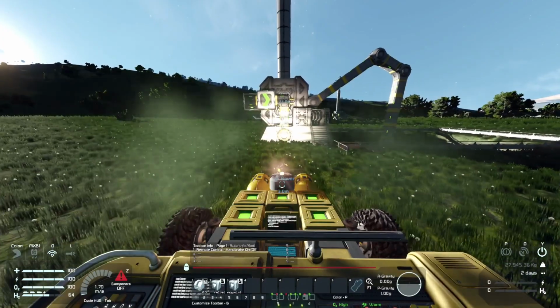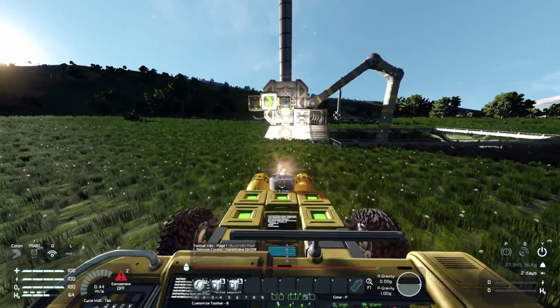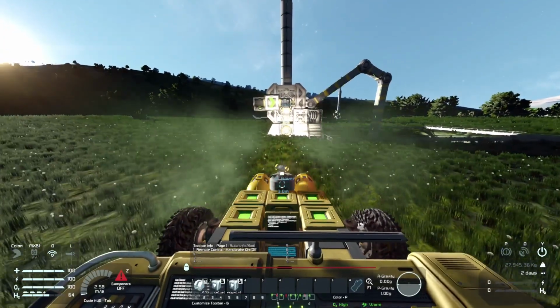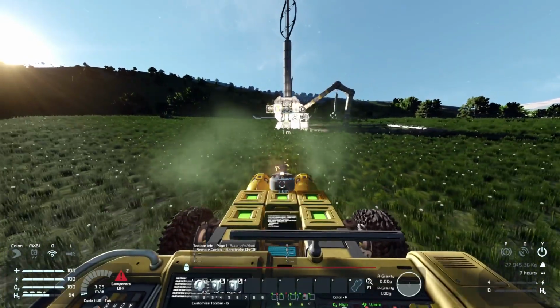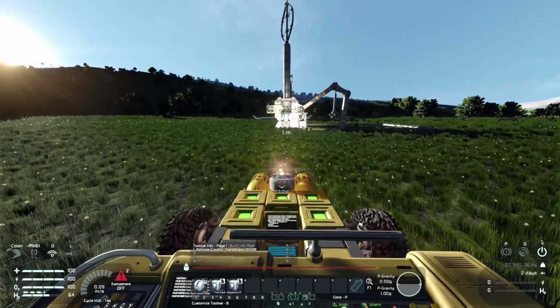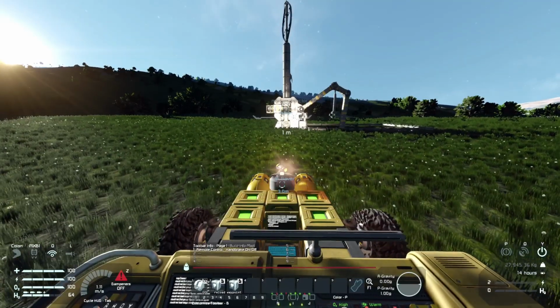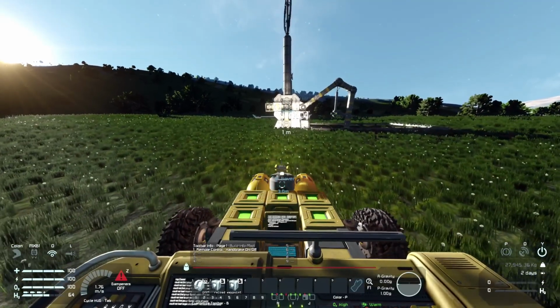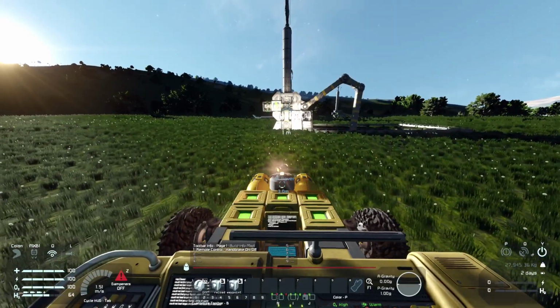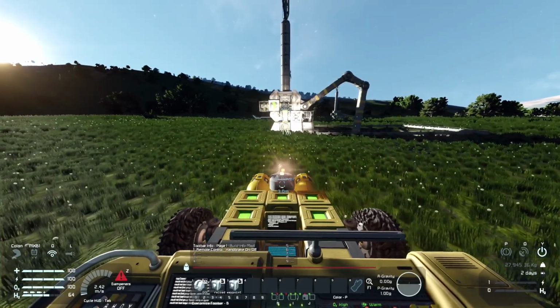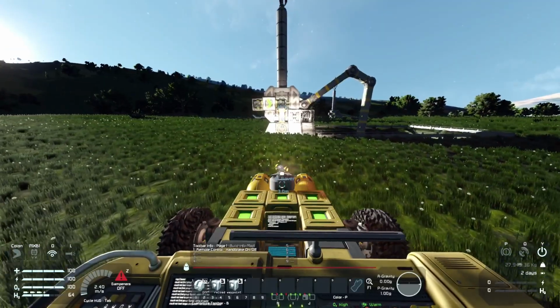So now that we've disconnected, we'll just pull back about 50 meters from the connector and add a waypoint. So these next 3 waypoints are going to be just for getting the rover well lined up with the connector.